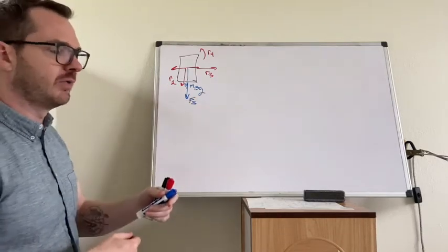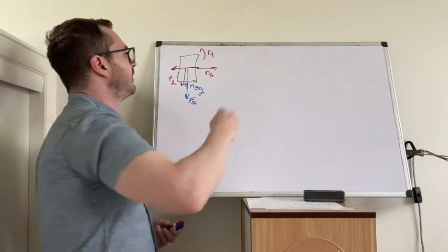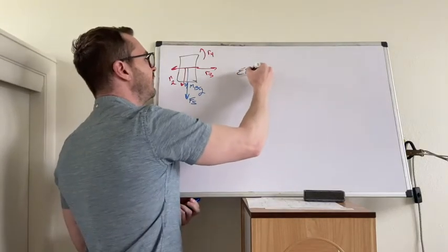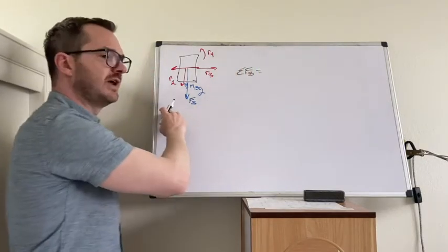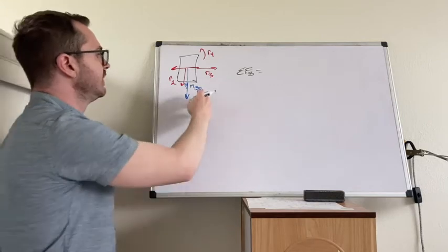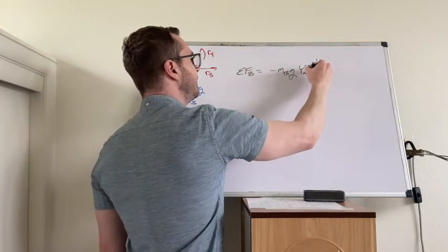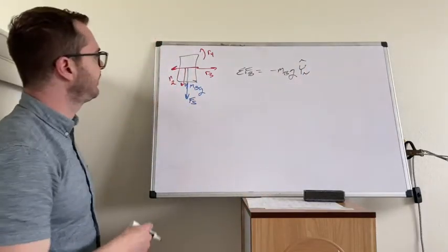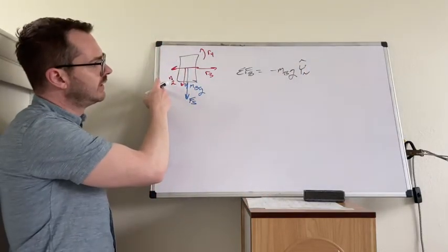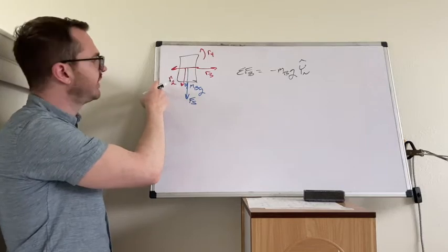Let's just write out the math equations now. So we have sum of forces on B. Let's just take each of these and bring them over. Let's start with gravity, minus mbg in the y hat direction. Next, let's do the reaction 2, this set of reaction forces.